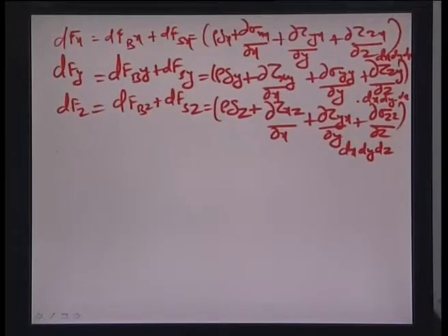So from Newton's second law, if you consider this control volume, the amount of force df that the control volume would actually face is nothing but m, the mass of the control volume, or delta m times dv by dt, where v is the velocity of the particle at a point P, and it changes to v at x plus dx, y plus dy, z plus dz at time instance t plus delta t respectively. We did this derivation, as a matter of fact, just before we started considering the stresses in the control volume, when we talked about acceleration.